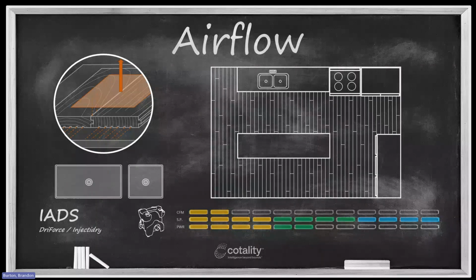Because we're extracting, that air is then being removed from underneath the hardwood floor and creates a negative pressure underneath the hardwood flooring planks. That negative pressure causes a pathway for airflow through the flutes. So air is drawn from outside of the mat area under the floor to the area underneath the mat, then up through the tongue and groove joint, and then is extracted by the blower and blown most likely outside. And we can talk about that more in just a second.